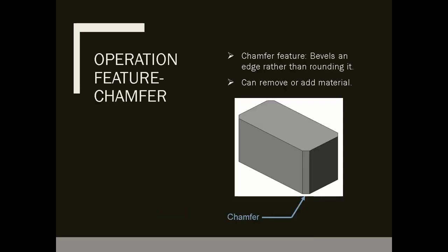Then we come up with the chamfer. It's very like the fillet, but it bevels the edge rather than rounding it. It also can add or remove material. You can specify different angles and distance or length for this feature.